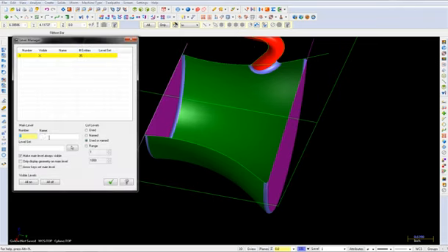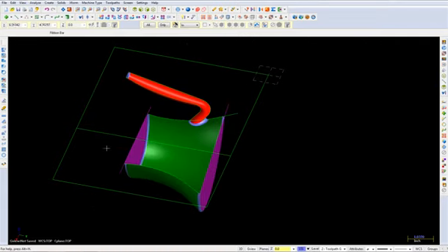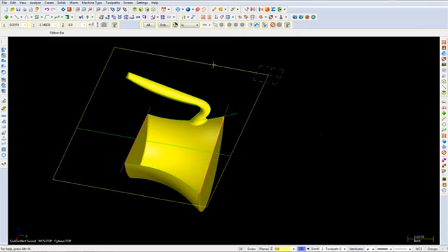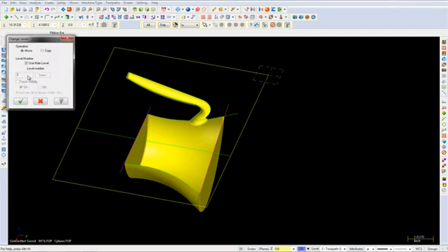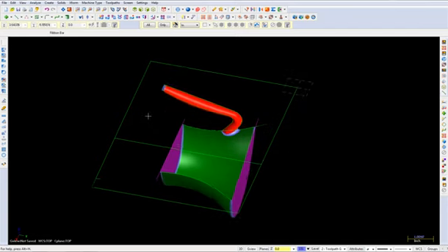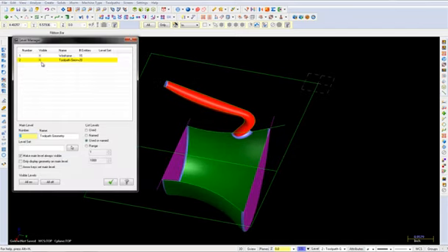Left-click on Level and name Level 1 Wireframe Geometry. Create another level on the number 2 and rename this to Toolpath Geometry. Select the OK button once complete. Now we will move all of the surfaces and the rectangle to Level 2. Quick mask on surfaces by clicking on this button and then hold down Shift and select this rectangle here. Right click on Level and move this to Level 2. Select the OK button. Then left click on Level and make Level 1 invisible.